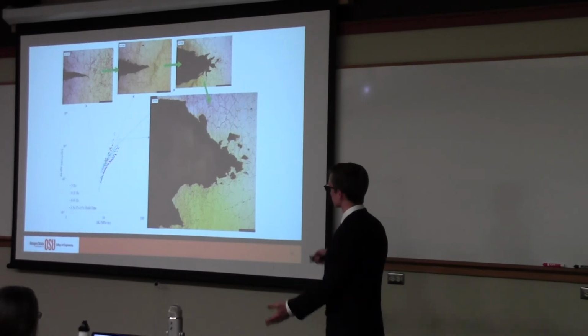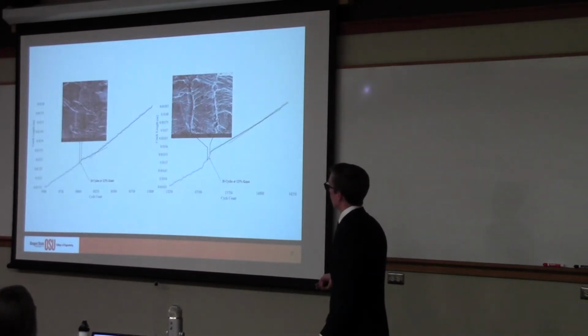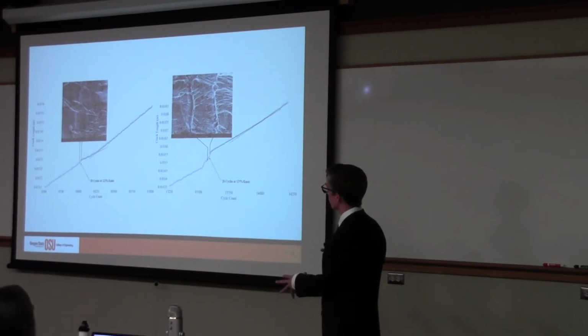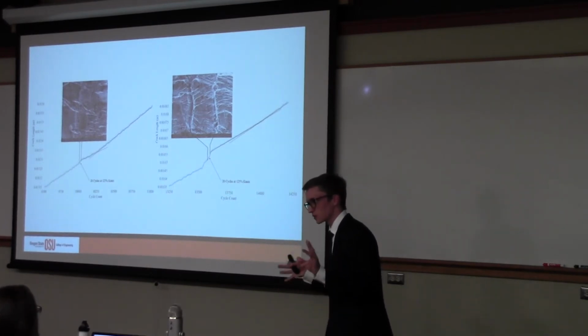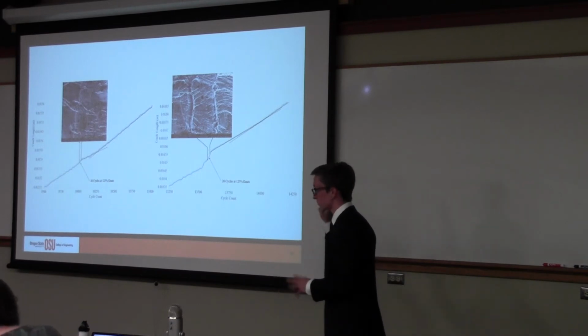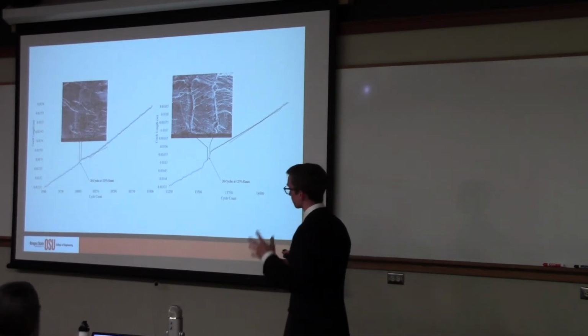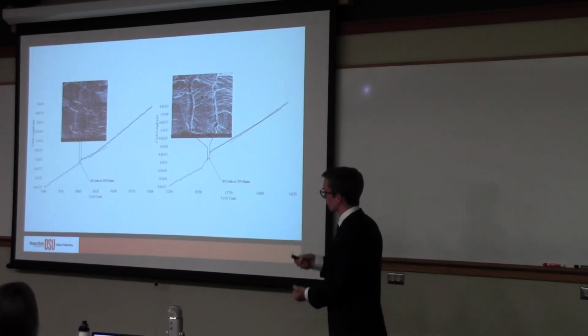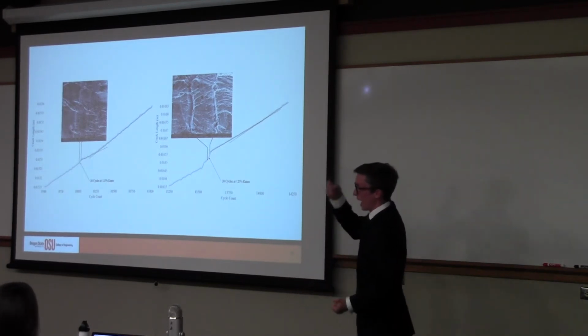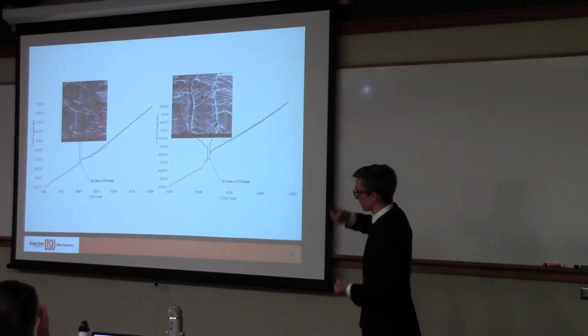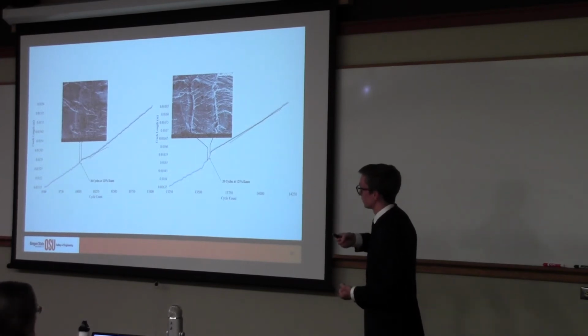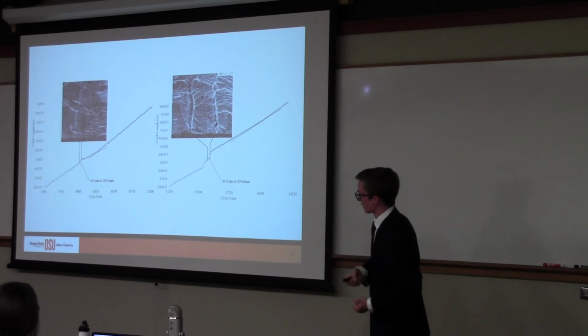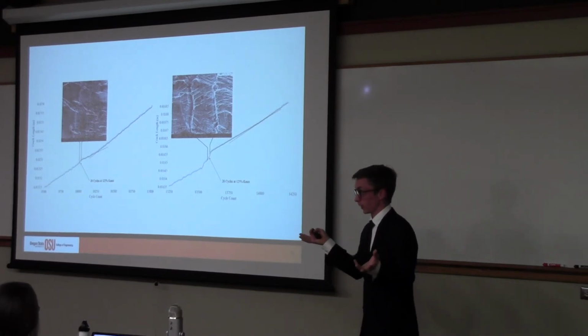And that's what's happening. It's clear as day. I'm not going to say too much about the overload experiments we did, other than it relates to stress relaxation, and these are some of the results. And so what were we really doing here? We were cycling at 0.33 hertz, and then we add a higher stress intensity cycle for 20 cycles or so. And then we go back to normal cycling, and we see if the crack growth rate was retarded or not.